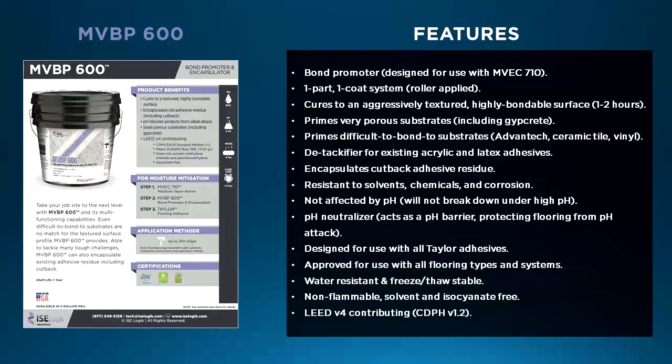This primes also very porous substrates, including gypcrete, etc. Primes difficult to bond to substrates also, ceramic tiles, vinyl floors, etc. It's a detackifier for existing acrylic and latex adhesives, encapsulates cutback adhesive residue, resistant to solvents, chemicals, and corrosion, and not affected by pH. So this will not break down by high pH.